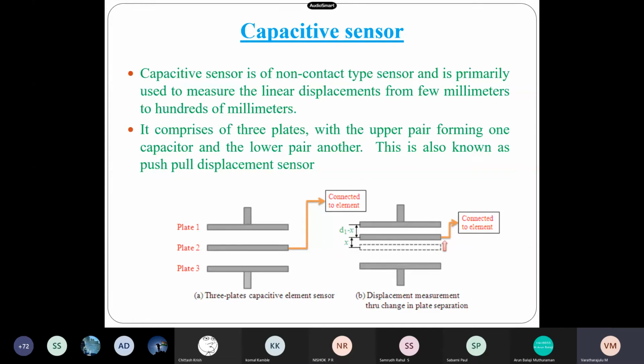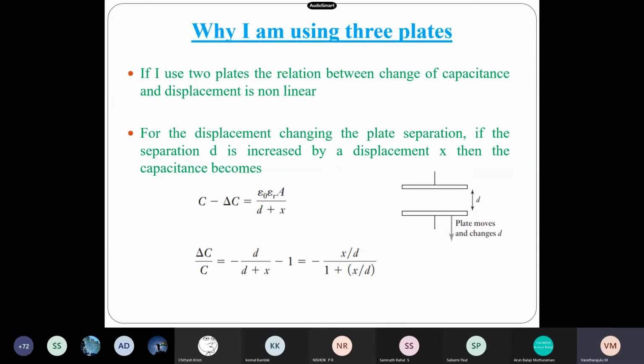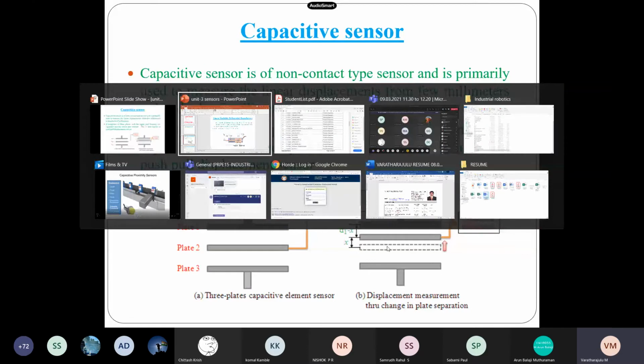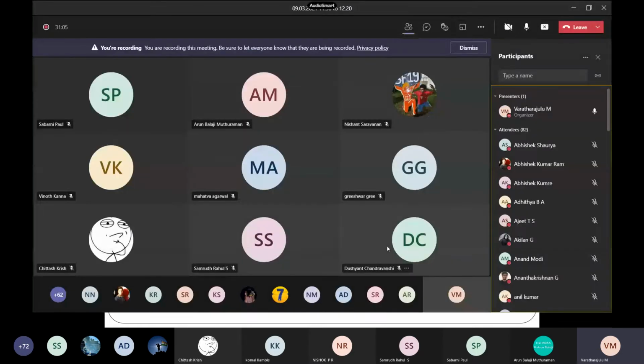But capacitive sensors won't identify those things which I have told earlier. Inductive sensors are usually used in elevators, and capacitive sensors are usually used to identify liquids and dielectric materials.